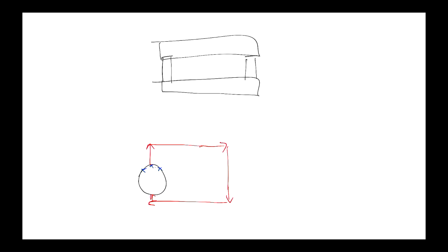Don't get stuck into C coding before you think about conceptually, in terms of bubbles and transitions, how this works. The problem with trying to code something in C while you're developing it is it gets very messy. You make changes, you get confused. It's much easier to conceptually lay out the state bubbles, and then translating that to code is straightforward, as long as you get that conceptual arrangement of the FSM right.